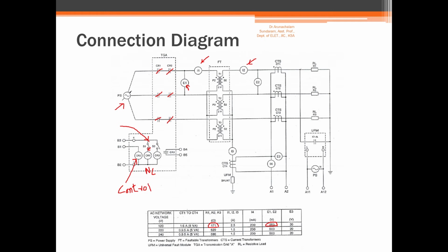So when you energize, you will find that there is a current flowing on the primary side which is measured by I1, and the line current on the secondary side is measured by I2. So this is a delta star connected transformer. So here we are protecting a delta star with the neutral point grounded. So this is the power transformer that we are going to work with. Now here you have to be very careful. Here you see that they have given you two connections. One is the voltmeter connection and another one is the ammeter connection.